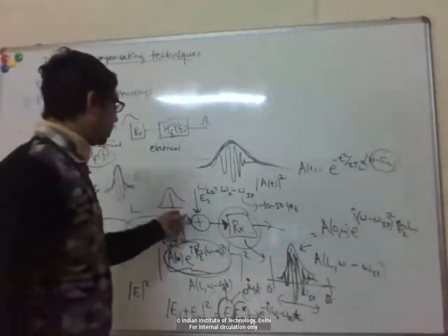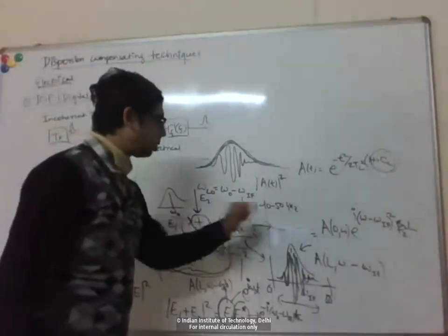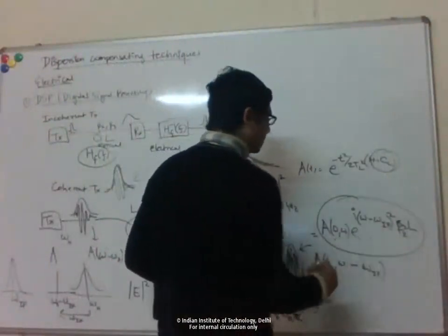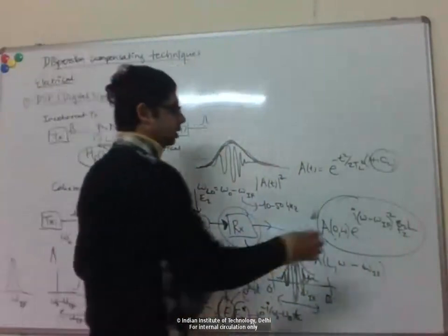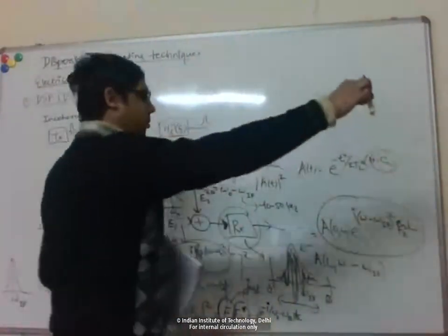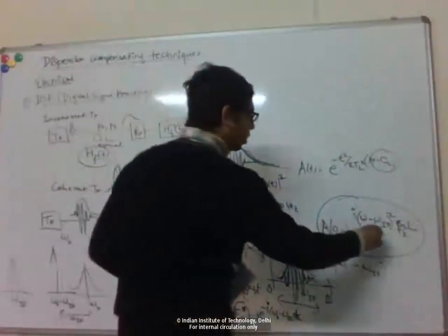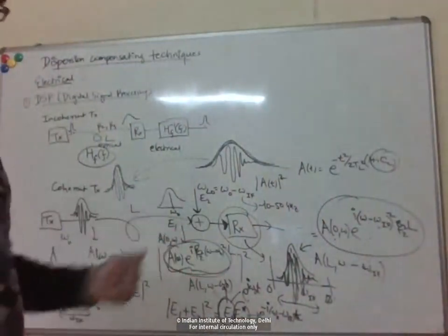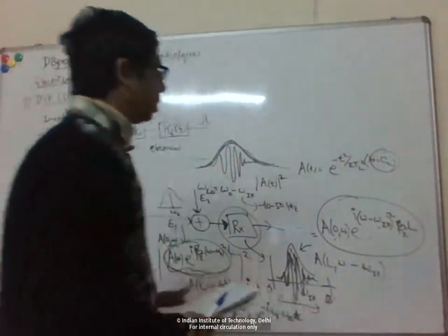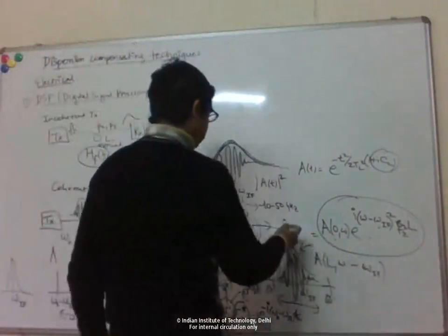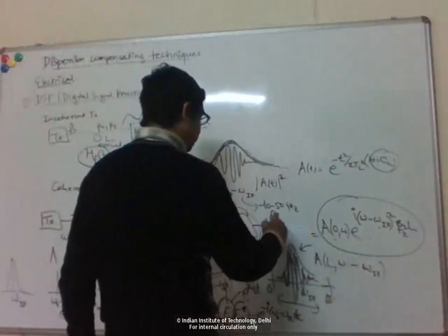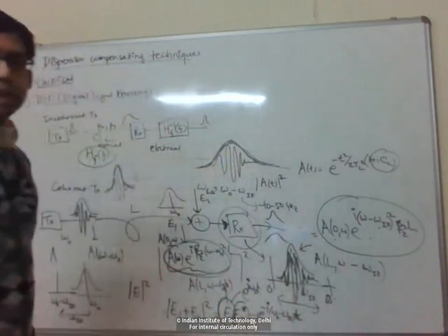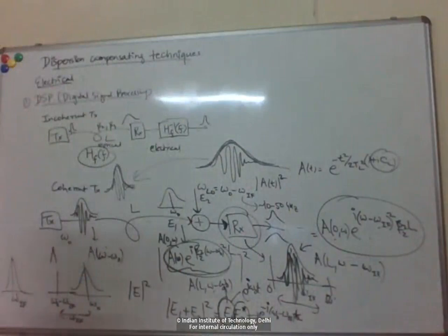Okay, so basically with this local oscillator beating, if you detect, the electric signal now has your complete amplitude and phase information, just with the frequency translated from the optical domain down to the electrical domain, because you are in the electrical domain now and you want to do electrical processing anyway, right? So now again you have a time domain and frequency domain signal here in the electrical domain, and you can use digital signal processing techniques. You can use digital filters, right?